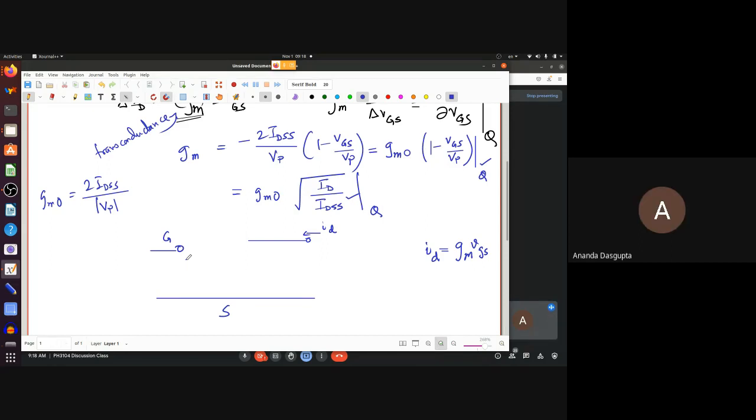Right. Now, I'm not very sure whether everybody is following this, so let me just explain this in a way. One way to get a current out of a voltage is to put an admittance in the path. We usually just put a resistance in the path and just use 1 by the resistance to find current out of voltage. However, that will give you a current between the terminals across which the voltage is. Here, on the other hand, the voltage is between gate and the source, and you want a current between the drain and the source. That you cannot get by using an admittance. An admittance is local.